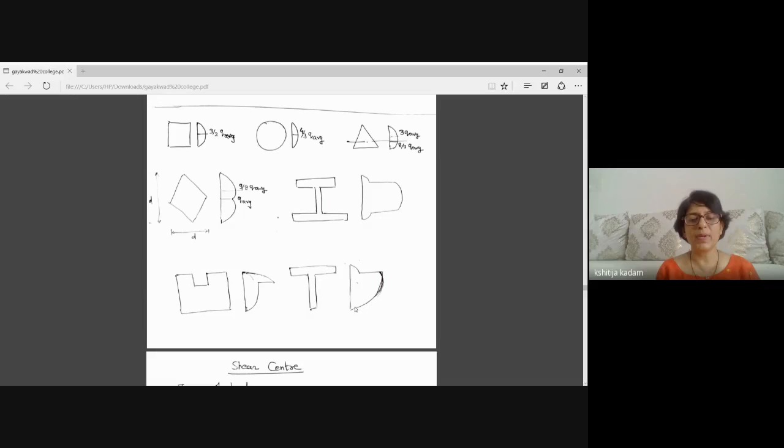And the same example you can see in the bottom sketches also. If you see the bottom left sketch, initially the width is less, so the stress diagram is more. Suddenly at the bottom of this groove, width has been increased, so the shear stress decreases.